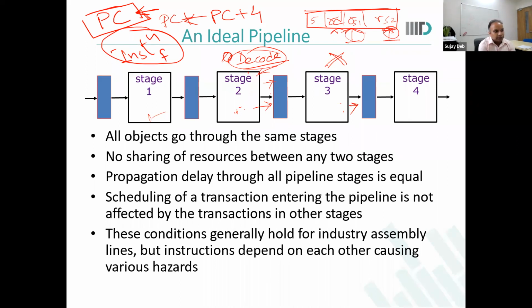So this is our execute stage. Now there are some instructions which need to talk to memory. So the next stage is memory. In this stage, if it is a load, what kind of memory instructions do we generally deal with? These are load and store instructions. In case of load, we need to load the value from memory to some register. Generally, from the earlier stages, either from the decode stage or from the execution stage, we get the address from where the loading needs to be done.